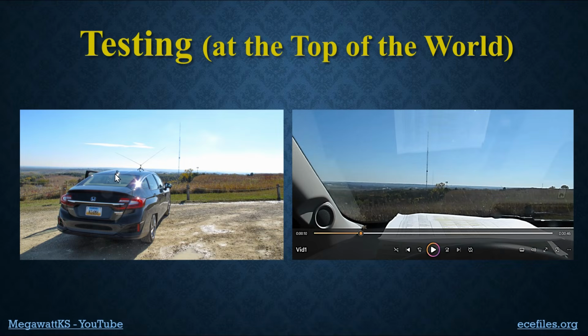I did some measurements on the car radio at home and then up here, and I found out that the sensitivity of the car radio, whose antenna is right here in the back, the sensitivity of it dropped by about 15 dB. It switches in attenuators to deal with this. And that's why when we looked at this video, it sounded so terrible at 88.1 megahertz. It was partially because of intermods, but also partially because it had destroyed its sensitivity.